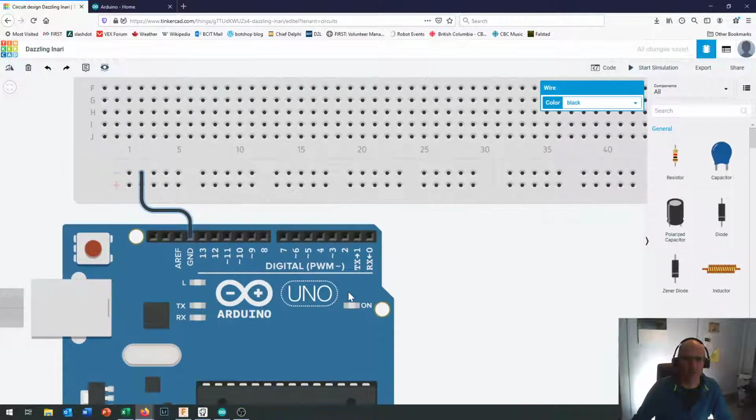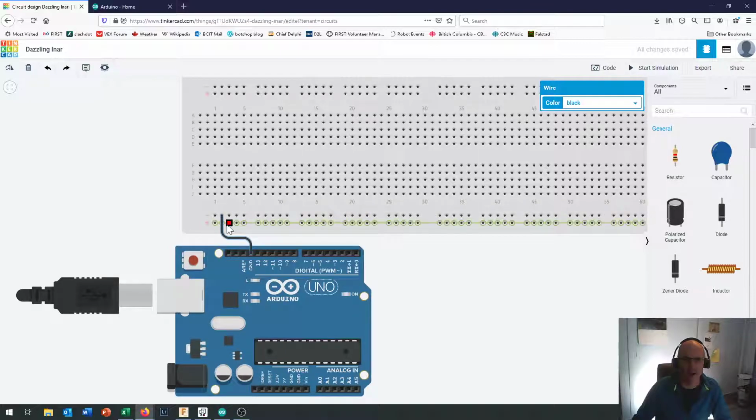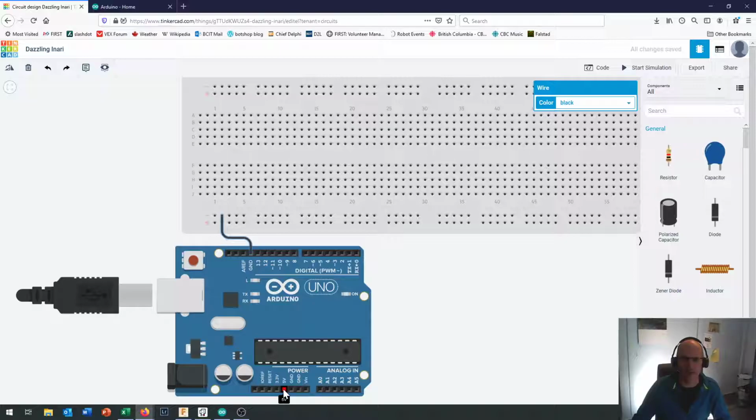And there is a ground wire, and that connects our Arduino right here to ground all the way along right here. So that's an important part of your component. Of course, if we're going to connect ground to something, we should also take our 5-volt line over here. Okay, and you can see your Arduino's pins are all labeled in here.